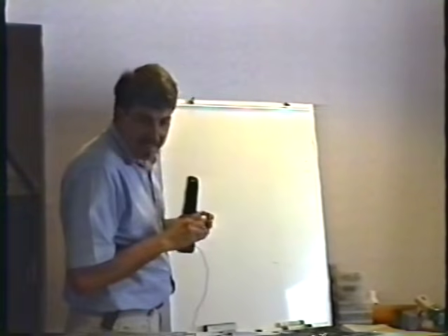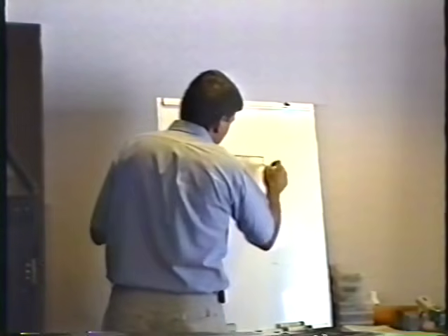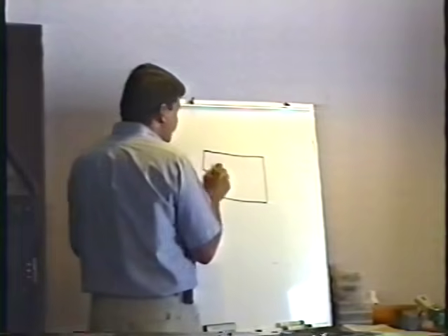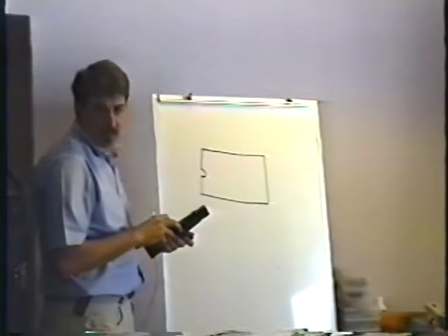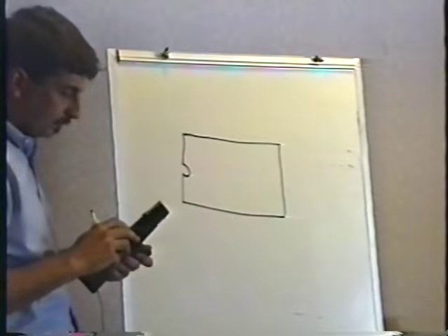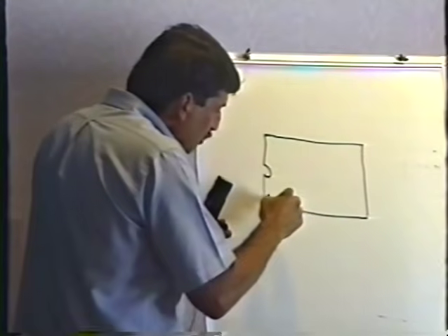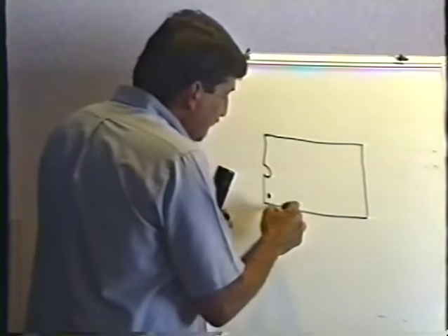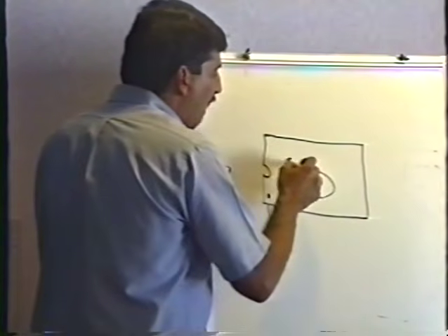When you look at the integrated circuits on a logic board, they look like this. They're not quite this big, but they look kind of like this. You'll see a notch at one end of the integrated circuits, or you will see a dot in one corner like that. And this denotes pin number 1, and the pins are numbered counterclockwise.